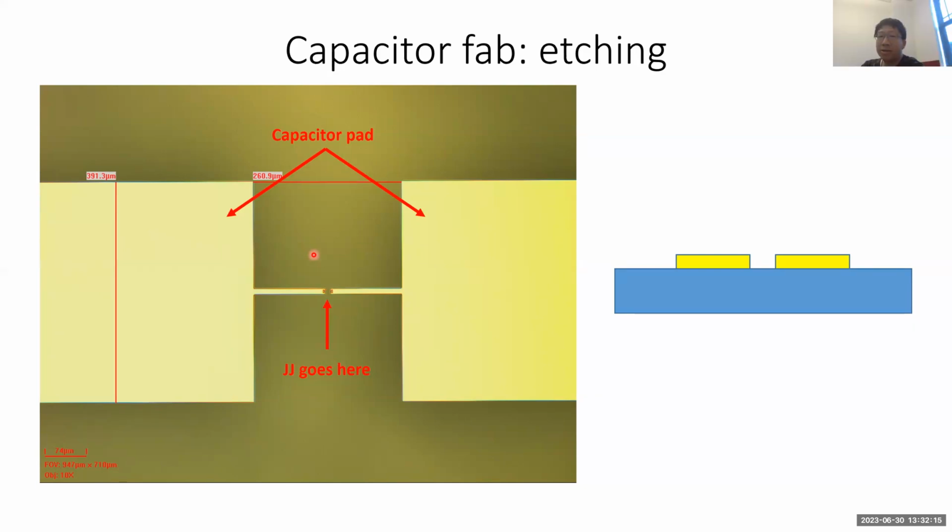So there's also a question on the impact of strip on the metal, like niobium or tantalum. It's not exactly clear to me what the question was, but I imagine it's whether the process of stripping away your resist is going to impact your metal surface quality. Yes, it could. If you don't do a good enough job, it can definitely leave some residue. The nice thing about working with materials like niobium and tantalum is that they're highly chemically resistant.